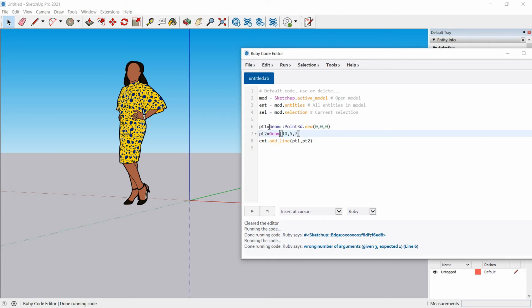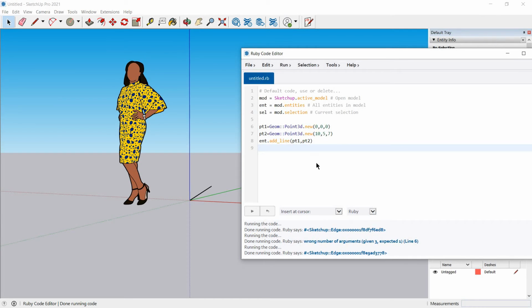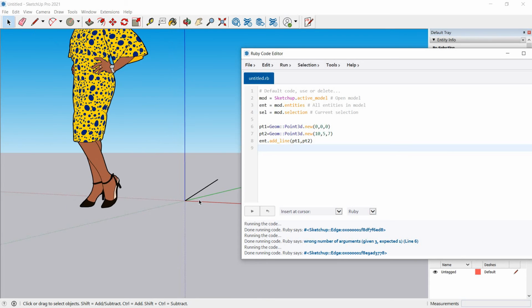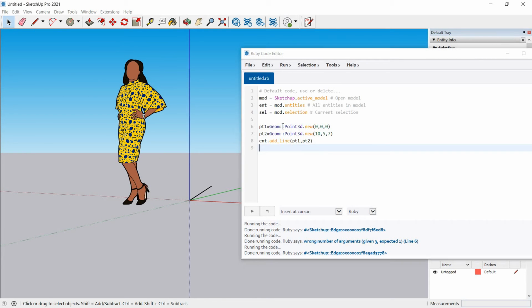So the same is over here. Point3d.new, then use small brackets. And press Ctrl R to run the command and it will give the same result. This is a long line of code, so we usually don't use this, we prefer the short one, which is to use big brackets and put the 3 coordinates over there. And you also need to understand this short line of code.